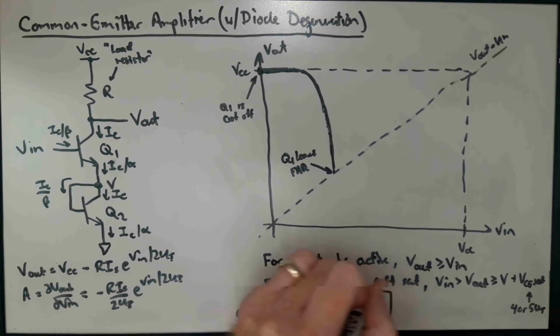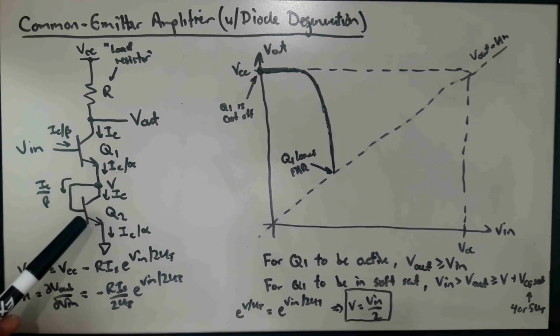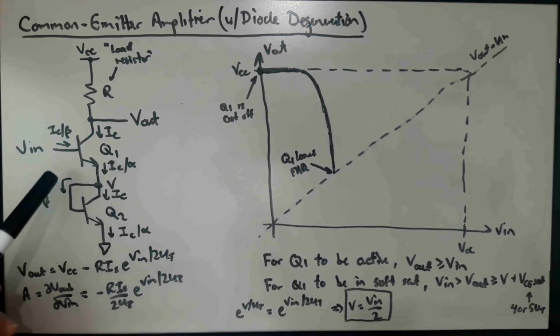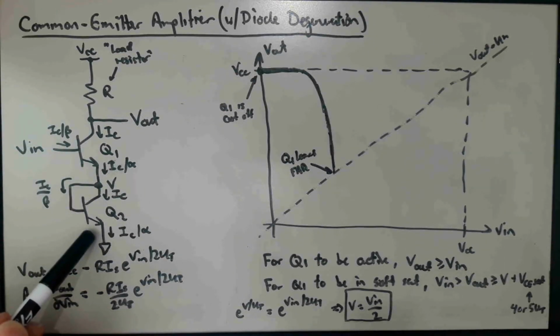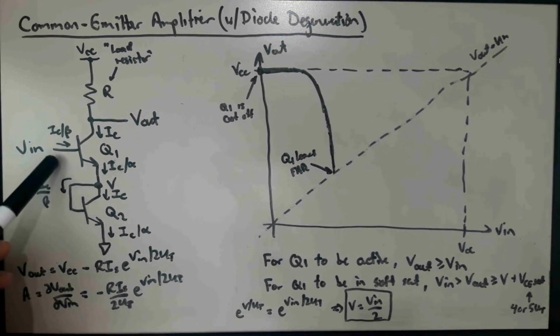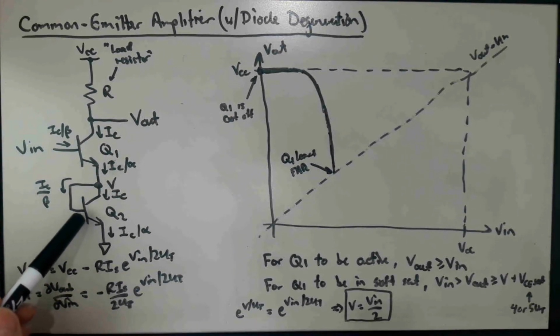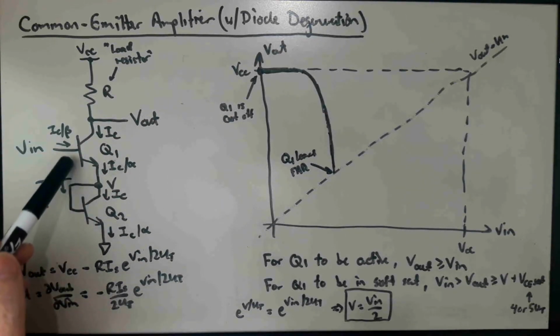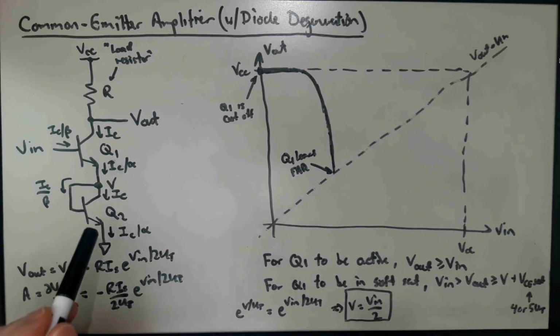with this result, because it may give you the impression that these are just acting like resistors, like a resistive voltage divider or something like that. And this is not a resistive voltage divider. Okay, please get that out of your head. These two devices are nonlinear devices. We're not approximating them as resistors. These are highly nonlinear devices. They happen to be matched devices, and so for the same current, they need to have the same base emitter voltage. Okay, that's what's going on here.